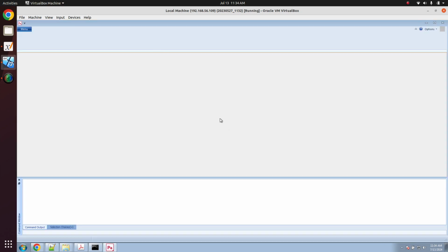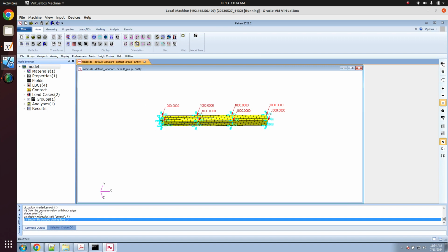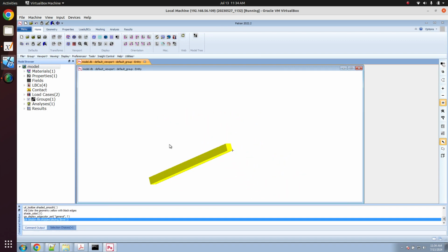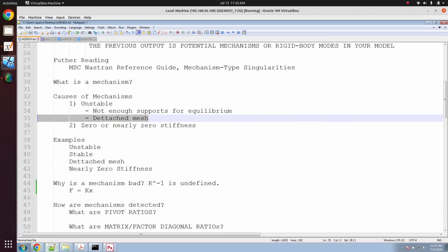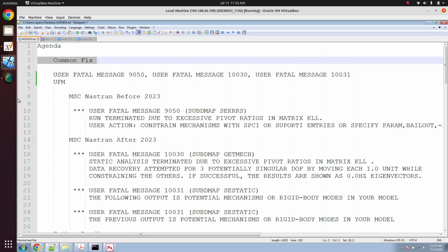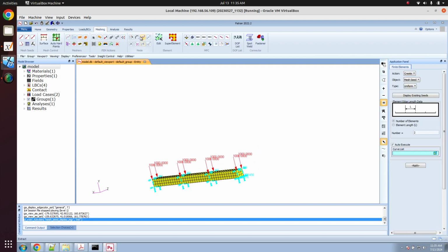And when you look at this model, it's going to look like it's one continuous mesh. And if you remember at the very beginning, I said that the most common way to fix this issue is to go to meshing and click on the equivalence button and click apply. This is the scenario where this equivalencing works. And now I get to describe why it works.